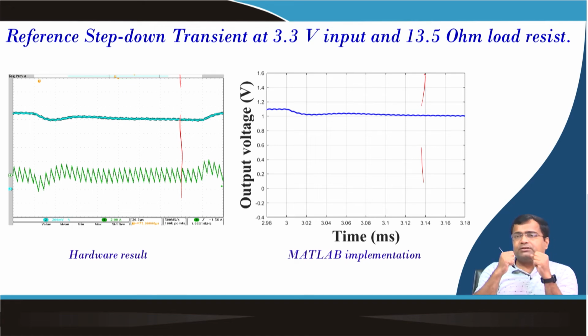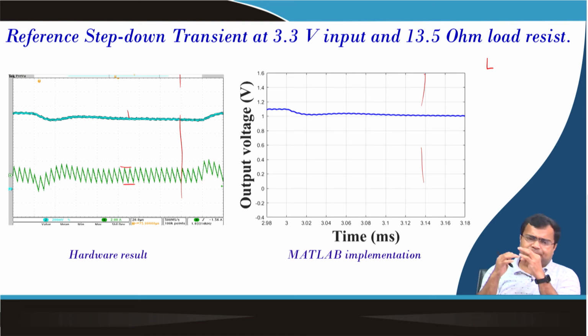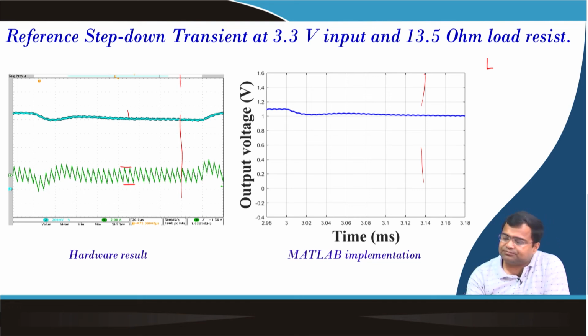So, which means we are able to capture the practical aspect, but to get this model we had to struggle, because in the actual we know the inductor value that can be obtained from this current ripple. We have measured the capacitor value, that was quite okay, that was 200 microfarad, although there can be some degradation in the capacitor, but if we ignore that effect, the challenge was, inductor will also have a DC resistance, right, which is RL.